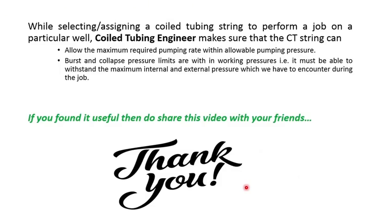The third criterion which the coil tubing string must satisfy is that it must be able to allow the maximum required pumping rate within allowable pumping pressure. And the fourth criterion is that the burst and collapse pressure limits must be within the working pressure range. That is, it must be able to withstand the maximum internal and external pressure which we have to encounter during the job. That's all for this lecture.